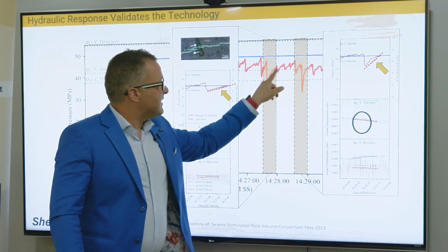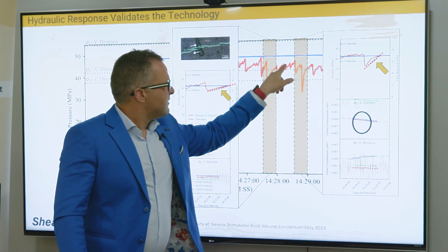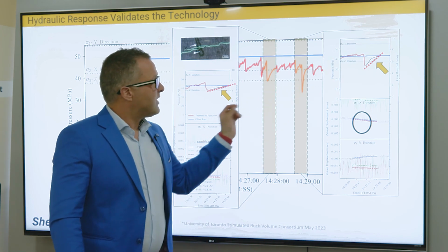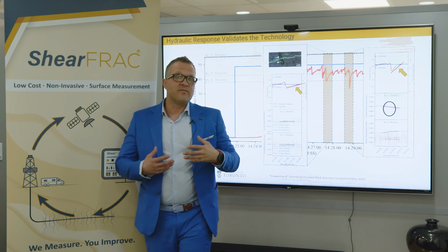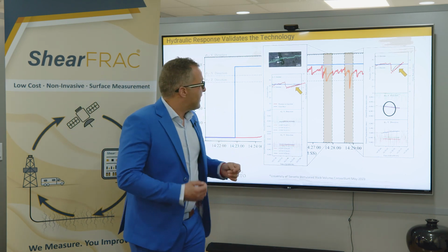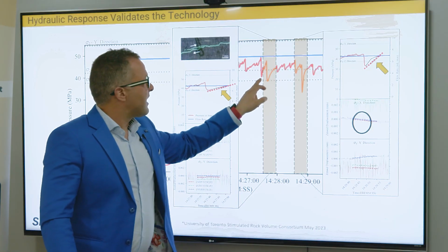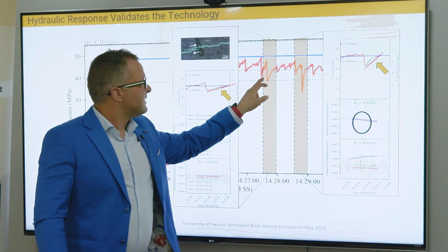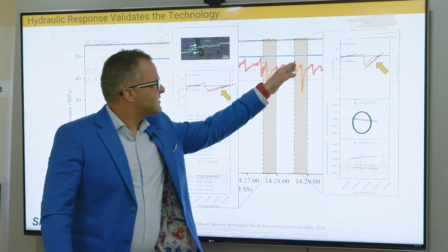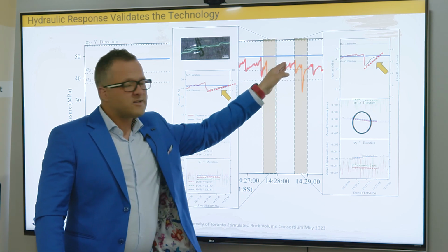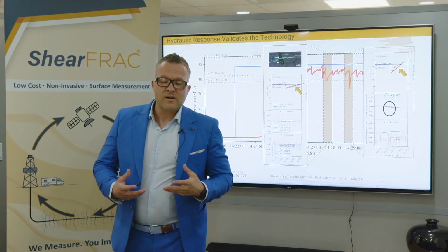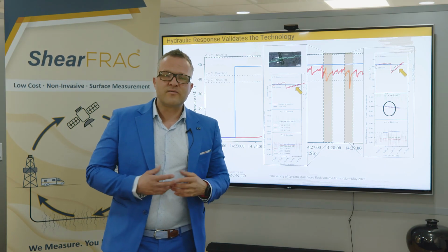Knowing this, we can integrate these recoveries during the pressure wave when you frac, and we can break these down into different fracture complexity. We can tell the complexity of a frac. The only way for a pressure to drop when you're fracking in a closed system is to open up a little bit more of the system. So each of these teeth in the comb is a new fracture opening. From the rate of recovery, we can tell the style of frac and break it out. So we know how complex your fracture is.